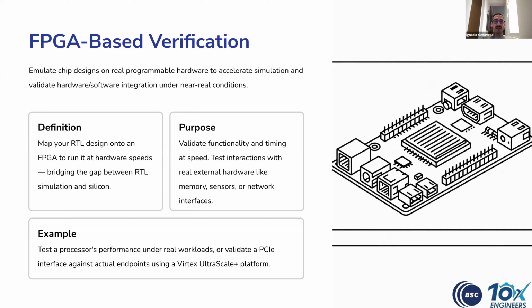The downside of this is that mapping this RTL into the FPGA might take a lot of time, but we might compress hours of simulation time on an FPGA. We can apply real-world stimulus, like connect our actual sensors, displays, peripherals, for authentic interaction of these peripherals with the design and testing them. And we can prototype our design earlier to validate complex interactions before fabricating the chip.